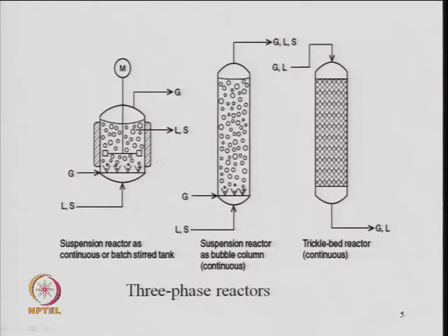So, you need an agitator to have good mixing. Basically the mass transfer problems are minimized by using this kind of reactor. So, gas is continuously passed through the sparger. So, a good kind of sparger is required. The size of the catalyst particle becomes very important. The bubble size, the gas bubble in the liquid. So, these sizes are important.